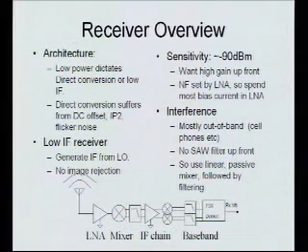So a low IF avoids these because you go to a frequency that's away from those DCs, so you can filter them, but still low enough frequency that it's cheap to amplify. And so then you put in some more gain, you boost yourself by another 30 dB or so, and then when you do the final direct down conversion to baseband, you've got 30 dB more signal before you have noise. So it's a better solution.